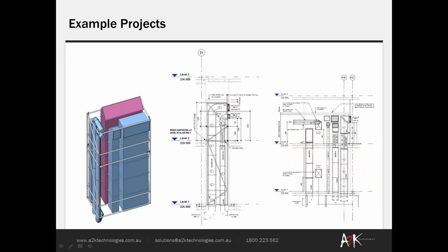And here's an example of a project that is basically all in Revit and it's fully constructible. All of these duct segments, and pipe segments for that matter, are constructible. They're built to size, and it can be taken off and built from this model pretty much. You can see the documentation as well, in terms of tagging and turning vanes, insulation indicators, all in there, all ready to go.